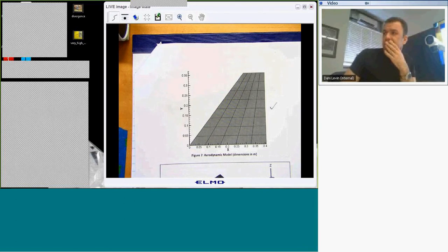Since we use a linear model, that means we can superimpose. So we do that for each of the structural modes of interest and add them all up together, and that gives you the total pressure on this wing. From the total pressure, you can find the generalized force, if you remember what the generalized force is. And what the code really outputs is the generalized force. They do it for simple harmonic motion in time, which, if you do not know it already, will be sufficient to do the flutter analysis.